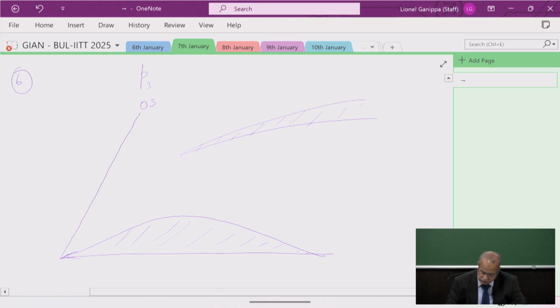Then the flow that encounters this oblique shock will turn by this angle theta so that it doesn't hit this one. So the flow turns, and before it enters into the inlet of this engine, it encounters a normal shock wave